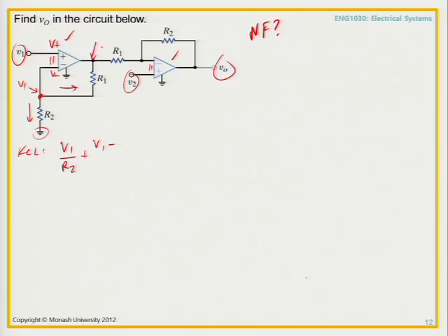Call it A. Excellent. Let's call it VA. All right, so VA over R1 must equal 0. Excellent. All right, so what can you do here? Well, you can rearrange this so that you get VA over V1 equals 1 plus R2 over R1, right? Why would I want to do that? We'll see. Okay, so that's for this bit.